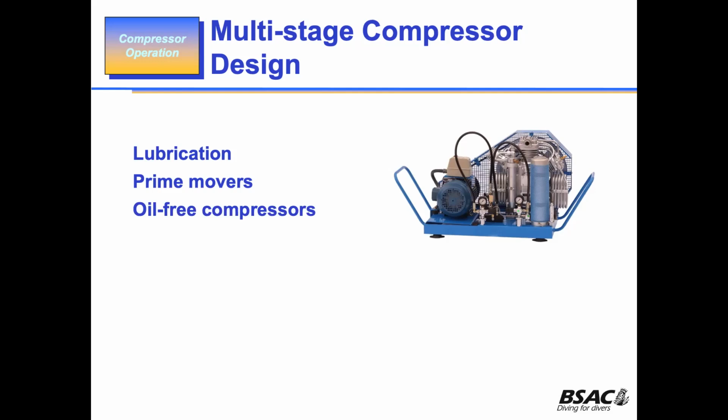You also get oil-free compressors. Oil-free compressors are basically for use in compressing oxygen. They do compress oxygen, but it's not the sort of thing you would do in a normal diving environment. But you can get compressors that will handle compressed nitrox. You mix it up, put it in, and away it goes. The thing about oil-free compressors is that you then do not get any risk of oil contamination.